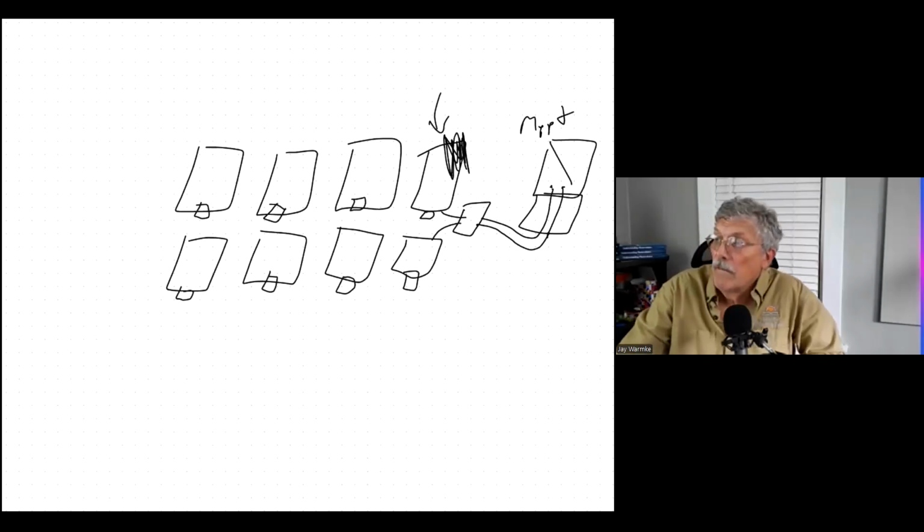So you'll oftentimes see string inverters, they might have as many as 4 MPPT ports. So every single string can come in into that inverter. But more often than not, if it's on a rooftop, these electronic devices on the rooftop have to be installed anyway because of rapid shutdown.